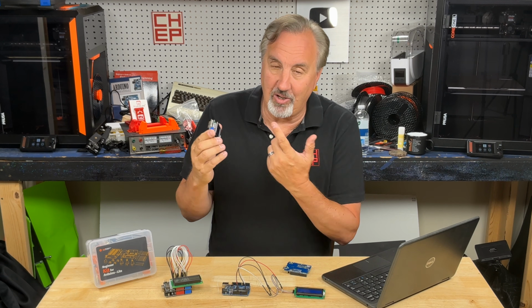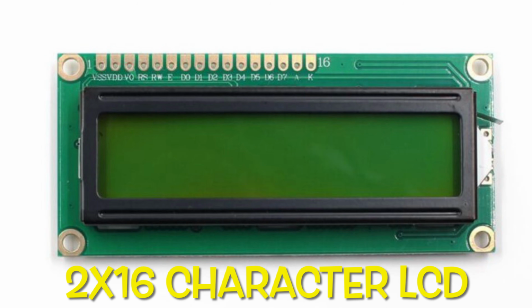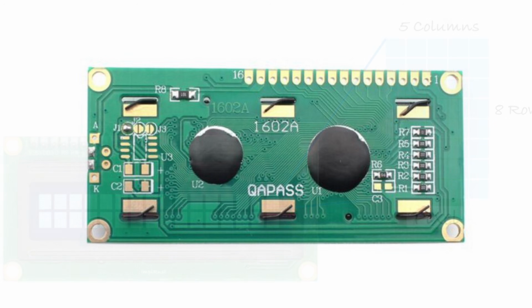But let's talk about what an LCD is for those that don't really know. A character LCD module can display numbers or characters or letters, and it does it in rows, like 2x16. So there are 2 rows of 16 characters, or 4x20 characters. There are different sizes. And almost all of them have a Hitachi 44780 controller that controls the actual LCD and generates the characters that you want to display.